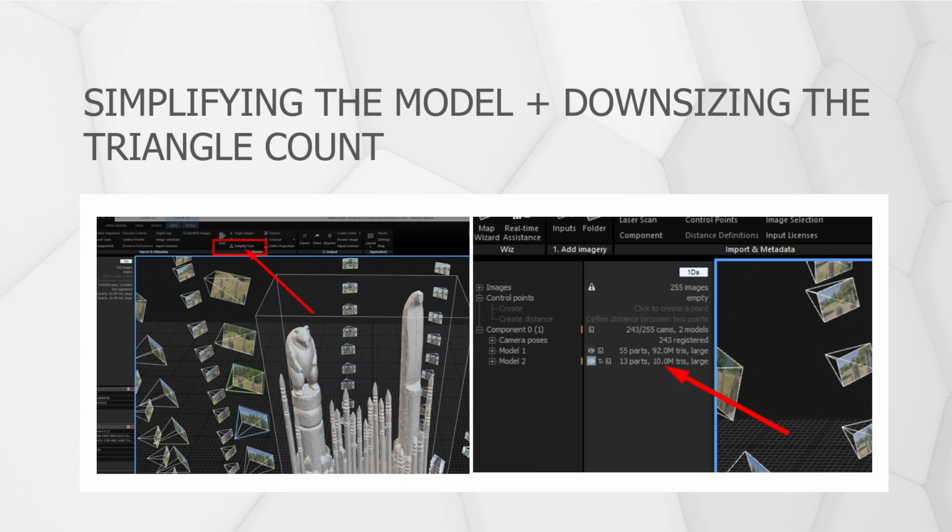The beauty with photogrammetry is that you can hide some of the low poly count with the texture layer. This is with the assumption that your texture layer is very high quality. So your texture layer is going to be your best friend to hide some of the imperfections that you see with a low poly count. Right, so a lower triangle count doesn't necessarily mean a bad end model. It just means that the texture is going to be doing more work to provide that detail. Exactly.